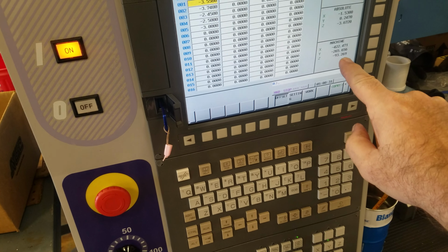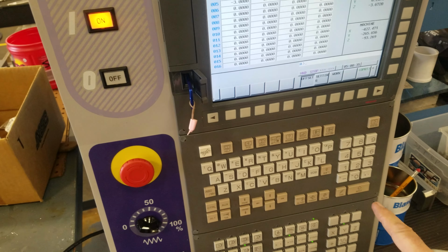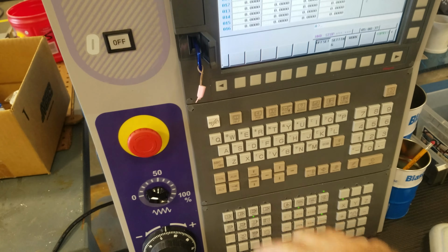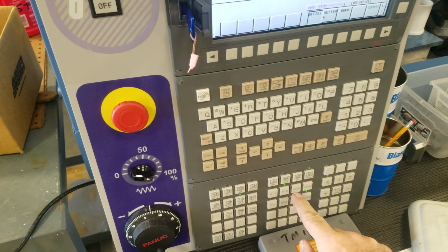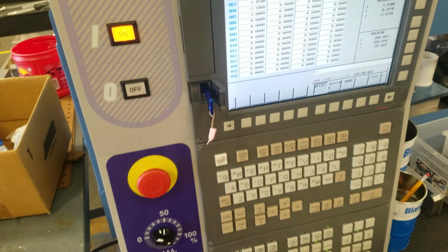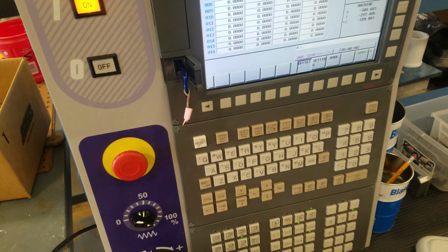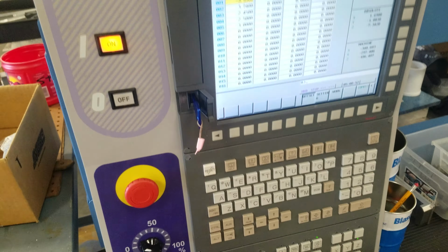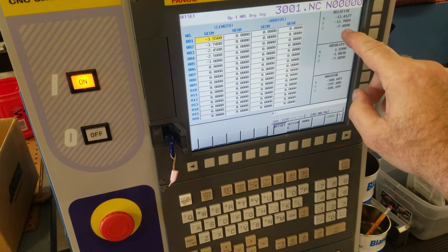And I'm really using the machine coordinate numbers, but I have my relative screen set to that. So I'm going to move the tool over to where the tool setter is. So I'll do handle, big number, X, move the X axis, move the Y axis, and then start bringing the Z axis down. And when I get close, I'm going to switch to 1,000th, bring it down, and when that thing touches off, I need that number there.